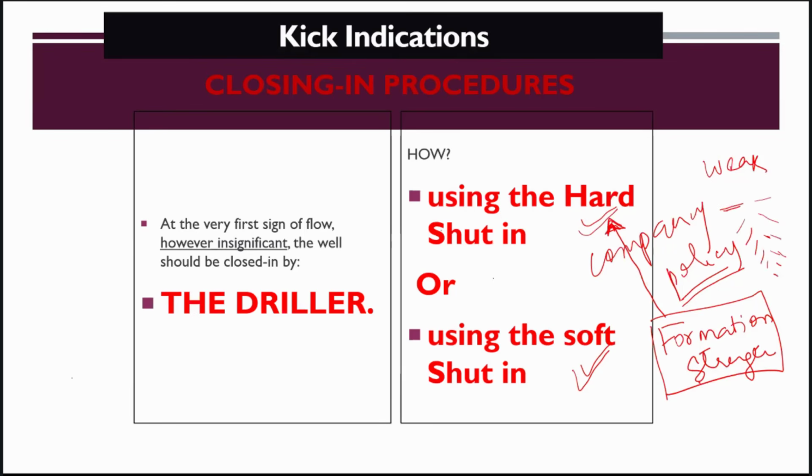Because hard shut-in is like suddenly you are blocking the way. Suddenly you are closing the well. So it is sending a shock on the formation, okay? There is a shock on the formation. So the formation should be hard enough to handle that shock.